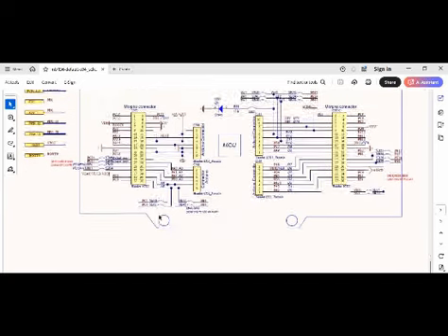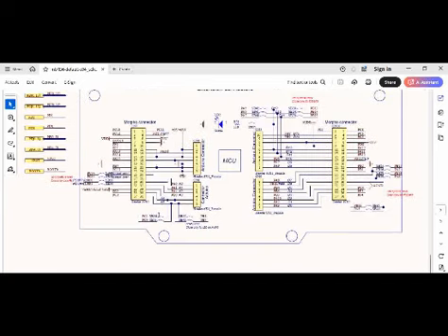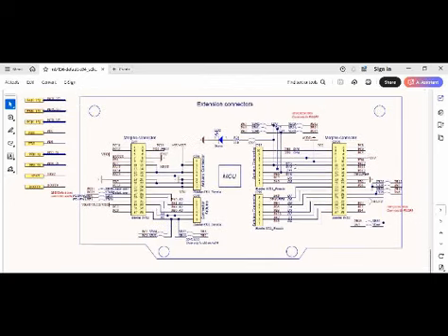So we have talked in our introduction video about the Arduino connector, and about the Morpho connector. So this Arduino connector you see here, and the Morpho connector are connected through some pins, and you see one LED here, LD2. Okay, so this is a green LED on the board with a series resistor of 510 ohms. Okay, if you are new to the schematic, you see some curves here. These are jumper shorting options.